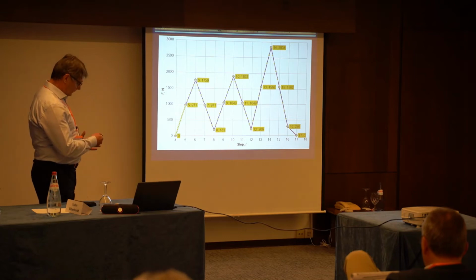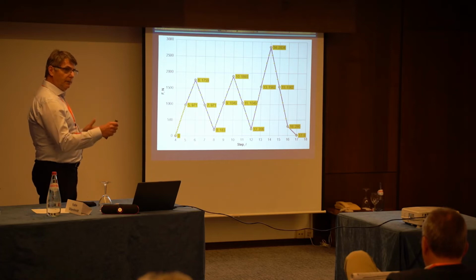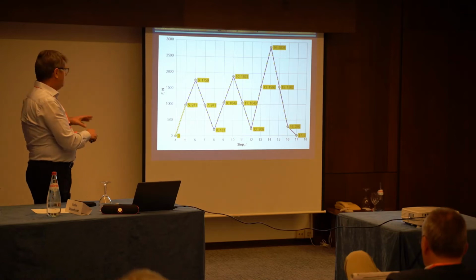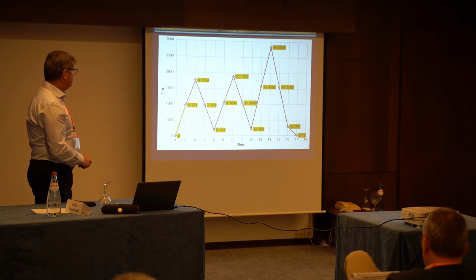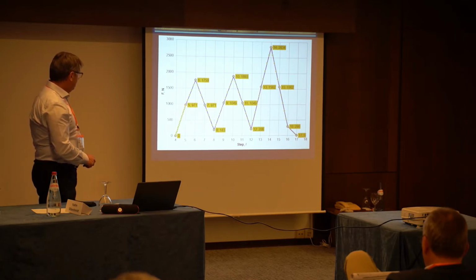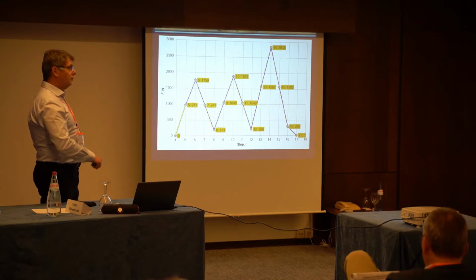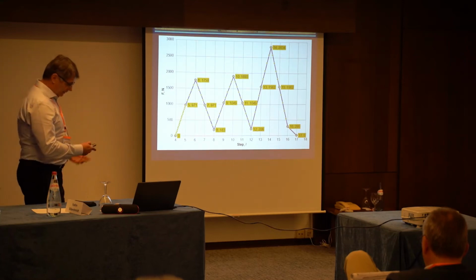Numerically, we make the step here. And it is difficult to talk about displacement now, because displacement will be the result of the load which you put in Abaqus. So we now start with the loading from 0, and this is our position, which is 0.5, 0.6, and so on up to this point. And you can see here the number of newtons which we achieve at this point. And this is our loading characteristic of cyclic loading of this specimen. And we now want to get the stable behavior.